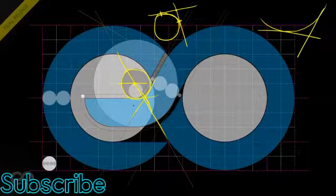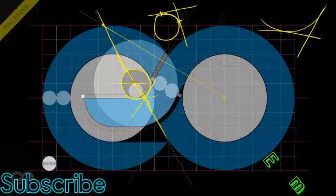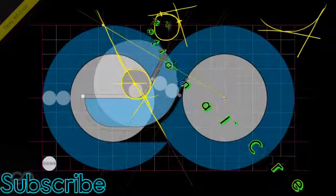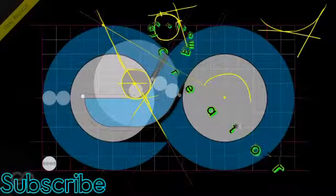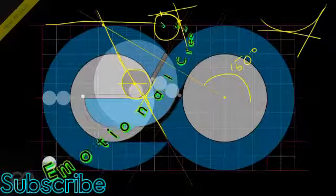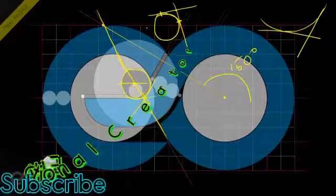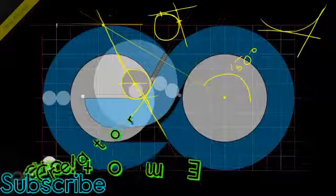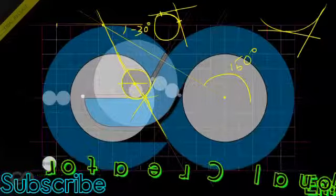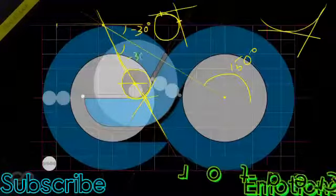So to create this, I'm going to make use of this line which I had created previously. You can see this was the line which was created from this point. So using this line, if I create a line which is half the angle, it will come exactly on this line. So what exactly is my process here now? If I create a line from here, you know that this is supposed to be 150 degrees. But if I consider that line from this point, so from this horizontal section, this is going to be nothing but minus 30 degrees. So if this is minus 30 degrees, then this is another minus 30 degrees.